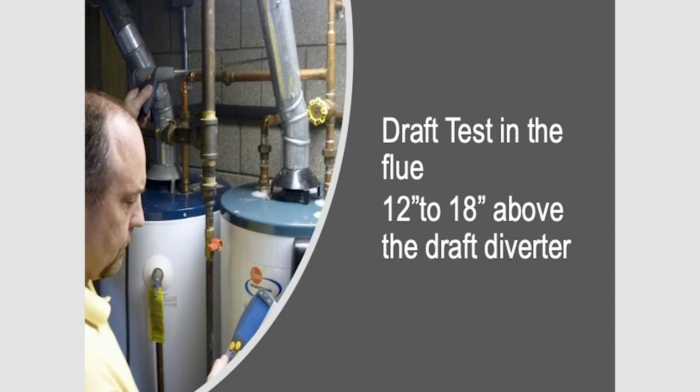Draft testing is one of the first things we do when we're doing combustion analysis. We want to make sure that we're going to ventilate those products up the stack. So a lot of times before I go in, I'll punch a hole in there and make sure I have some draft, make sure things are going to go up the stack. Sometimes you won't have draft, especially if the chimney's cold, but it's important to realize what you're walking into when you do this type of work. So let's talk about the function of the draft hood.